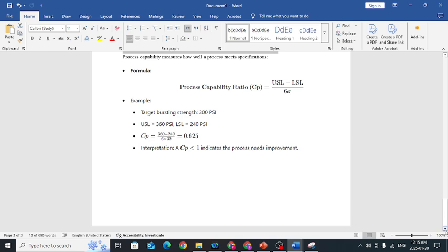So it's okay. But guys, before finishing this session, one more time, the key takeaways you should know: the control chart helps detect process variability and maintain stability. X bar and R charts are ideal for numerical data, while P, C, and U charts work for attribute data.